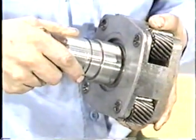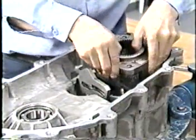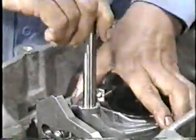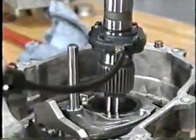Other than the missing high-low shift fork insert, everything looks good. Begin to reassemble the transfer case by installing the input shaft and carrier gear assembly in the case. Install the high-low shift hub, fork, and rail next, followed by the rear output shaft with the oil pump.